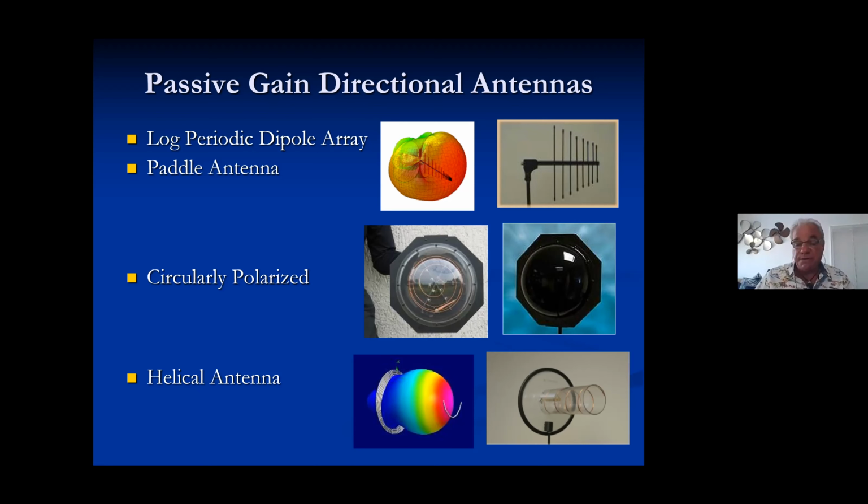I have a pocket full of various RF amps, but I don't use them unless I absolutely have to, and not until I have someone walk all of the transmitters out onto the stage and into the audience, to the furthest point that anyone expects that mic to work, and only as much as I need. When I use the Shure inline amps, I usually keep those to 3 dB. When I use the PWS, I keep them to 5 dB. I always start with the least. More is not necessarily better.